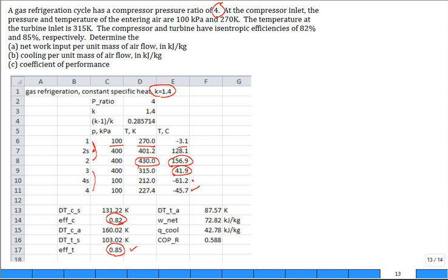All right. What's the coefficient of performance for this system? Not very good, 0.6. What was the COP of the absorption refrigeration systems that I talked about that are in RVs? The water, the ammonia, and also the hydrogen. It's down at 0.2, low, which means you burn a lot of propane to make it work.